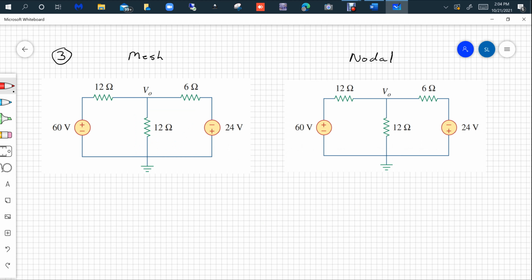Actual circuit. If you're doing mesh analysis or loop analysis on this loop here on the left-hand side, most likely your instructor is going to say clockwise, there's I1. As soon as you do that, put a plus there, a minus there, and a plus on that side and a minus there. And he'll probably have you draw a loop current in the clockwise direction, I2 there. For those of you that haven't had mesh or loop analysis yet, don't worry about this.